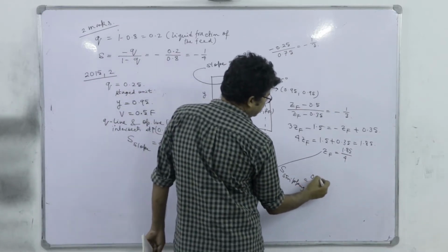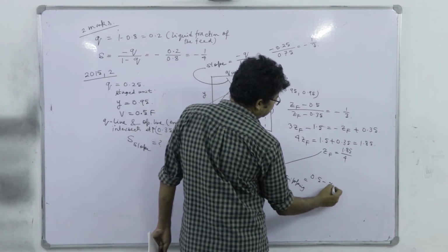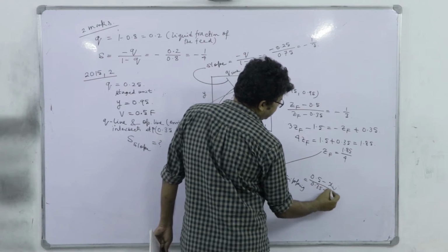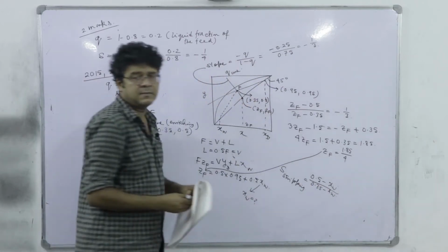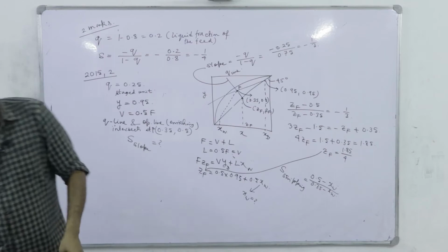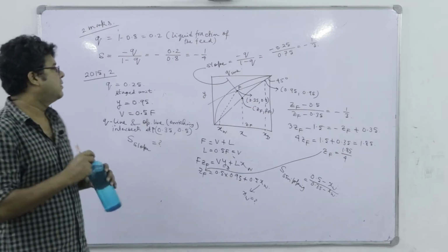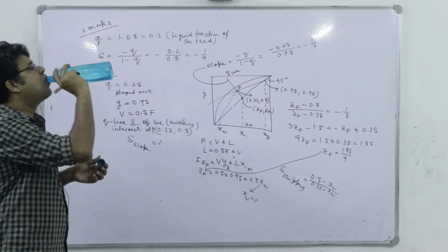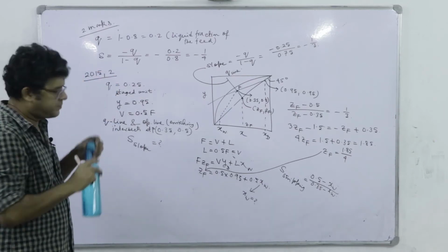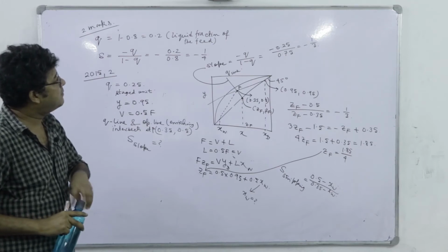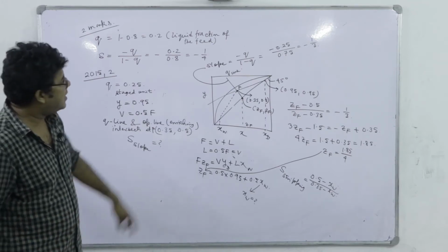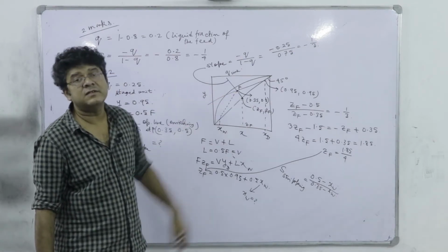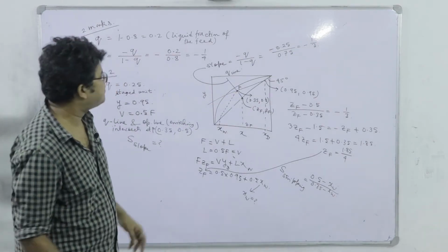So it is 0.5 minus XW divided by 0.35 minus XW. So that's all. In this way we can solve this problem and get the operating line slope of the stripping section. What is very important to note is that through this q line slope and knowing this point, we have to determine ZF, right.